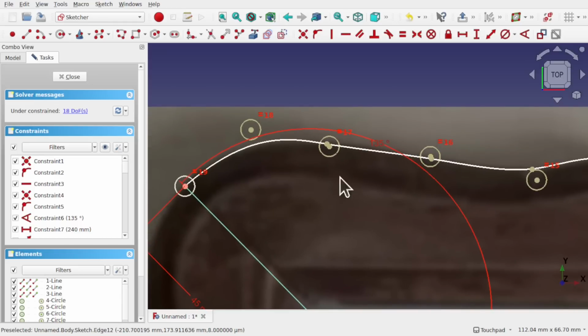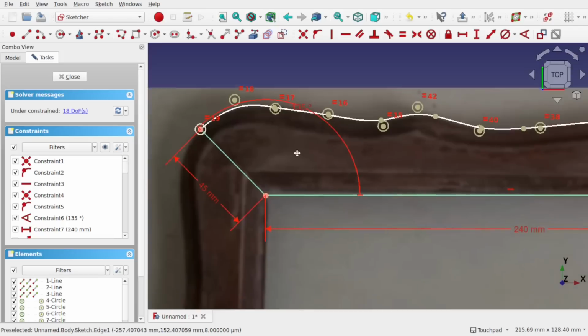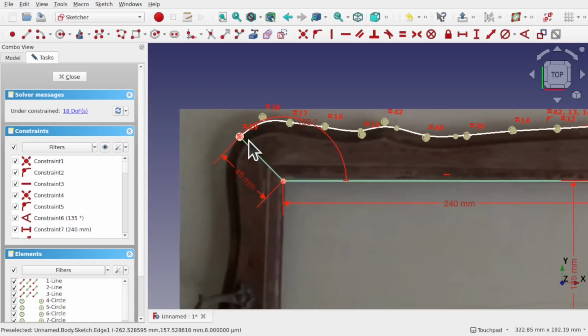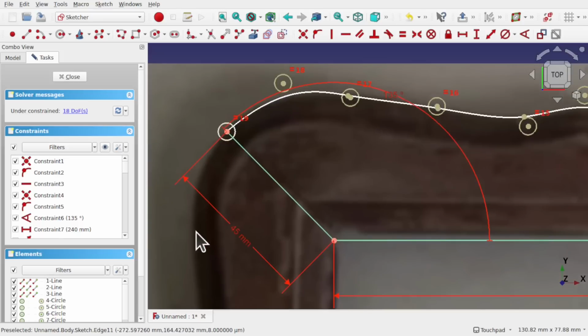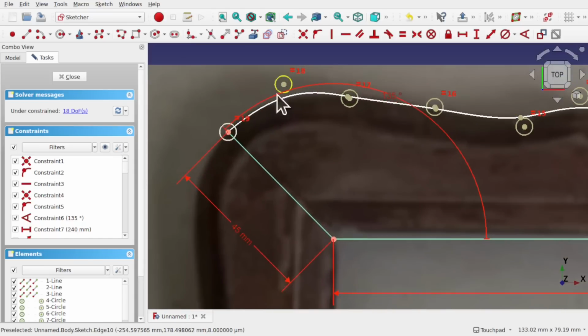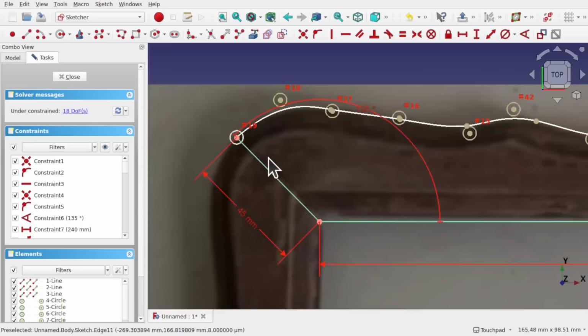Now I'm approaching this side and I have to be careful because I'm creating this as multiple parts. I have to be careful of tangency. So if we look at this here, we've almost got a circle. So we need the B-spline to be tangent to the other piece. So we have to be wary of that. So let's see if this fits a circle or an arc.